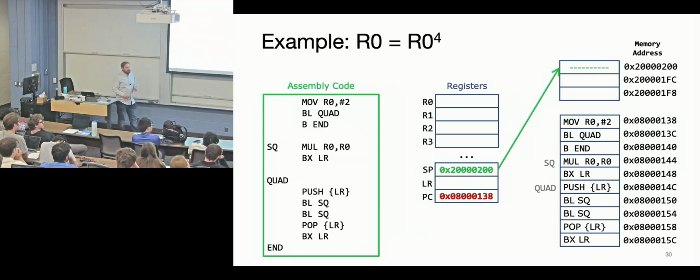So I guess just to clarify, if we're using the stack pointer, we have to increment it and then write what we want to it. It changes for you. But just remember that when you push something, it adjusts the pointer and puts data in. It's not going to put data where the stack pointer is pointing, it's going to put it in the next spot.